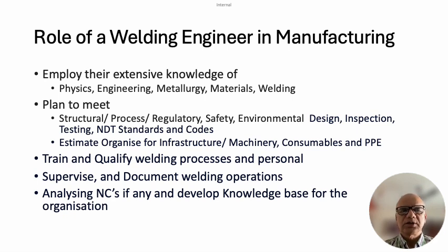If fixturing is required, that is analyzed in stage 2 in the plant to meet the structural integrity. You normally design a fixture, or for a process you have a fixture. If there are 2 nozzles which are required to be exactly 1 meter away, then you have to tie these nozzles 1 meter away and fix it onto a pressure vessel, so you require a fixture.